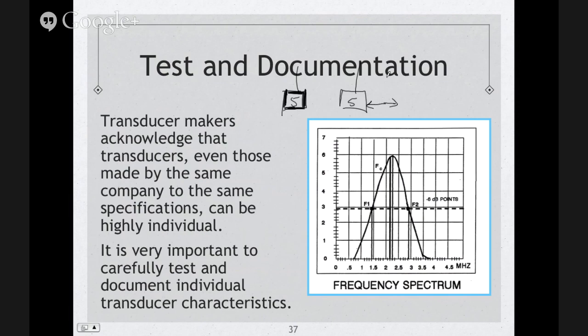You get this transducer because it's a 5 megahertz. It's the same transducer, at least frequency-wise and diameter-wise. But you get this one. Now you go ahead and do your calibration. Well, your calibration is going to be very, very close to the first calibration you did, but because you're using different transducers, not all transducers are the same. One is always going to be different from the other, even with the same person, the same machine, the same material, the same diameter, the same frequency, the same crystal thickness, all that. They're still going to be different to each other.